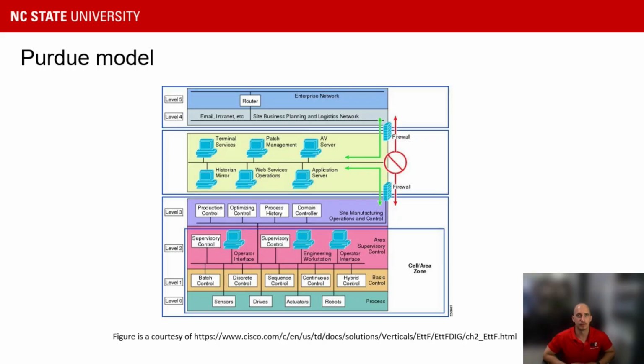Enterprise levels 4 to 5 retrieve only siloed data and cannot directly access the assets on the factory floor. A 5-layered model limits data flow in the context of smart manufacturing, and specifically in IT-OT integration in industrial IoT settings. The Purdue reference model also does not allow quick equipment addition and operation.